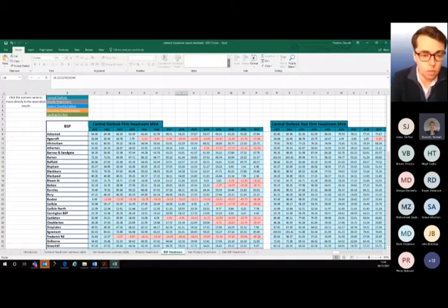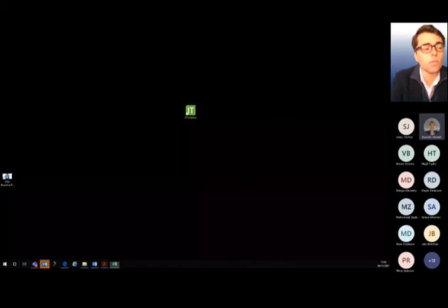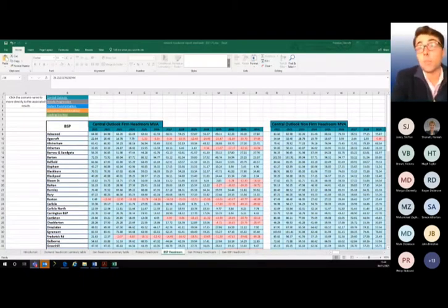Okay, that's fine. I'll just have a look. What does non-firm mean? Non-firm, it's when you apply, you can be given 2 options, firm and non-firm. Firm means that if there was an outage on the network that you're connected to, we would have the facility to be able to backfeed and keep your load on, or else allow your generator to generate onto the network but in a different part of the network.